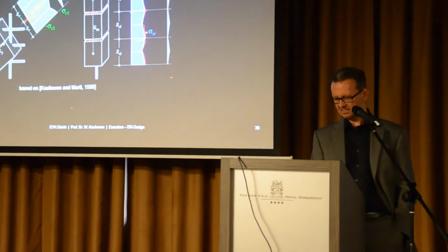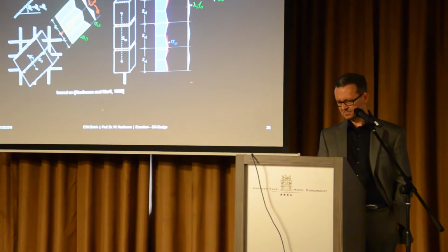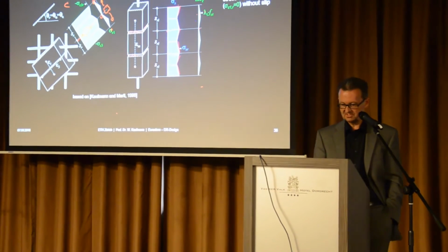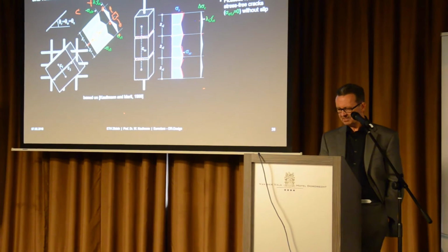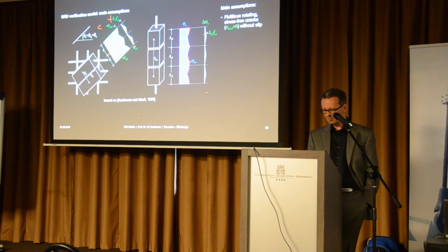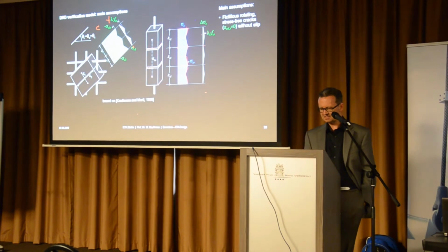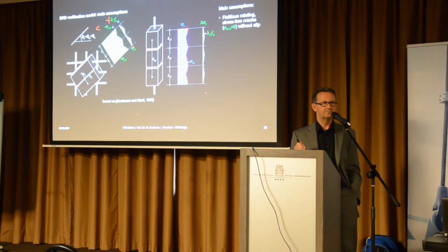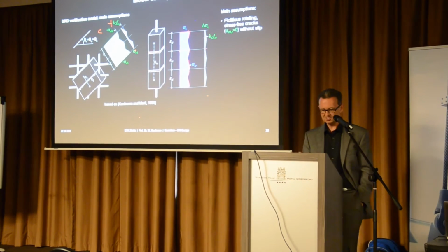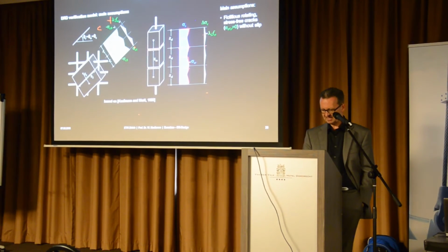And you can see that because both reinforcements have zero stress at the crack, of course also this crack will have zero stresses at the crack, but in between the crack I get some tension in the concrete, and now also my concrete compressive stresses between the cracks are a bit lower. This is an important point when I come back to the compression softening relationships. So at the crack we have a higher compressive stress than in the middle between the crack.